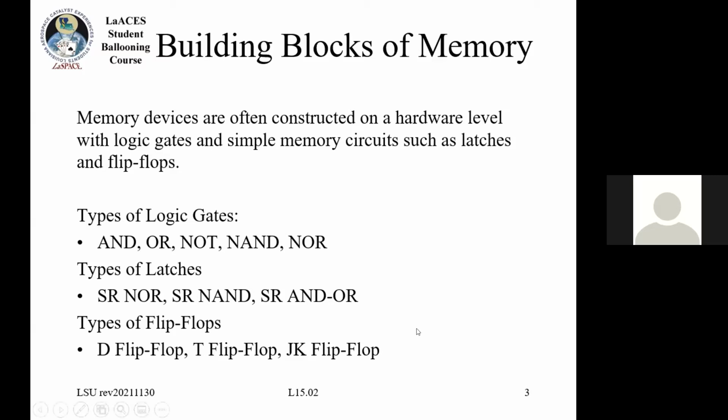And you can have an AND or an OR, a NOT, and then a NAND and a NOR. So a NAND and a NOR just apply a NOT to the result. You AND the 2 inputs together, and you invert the output, right? And the NOR is the same thing except with an OR.